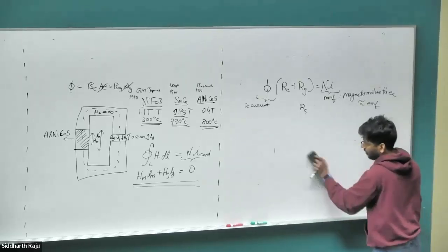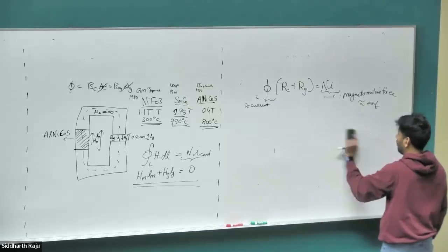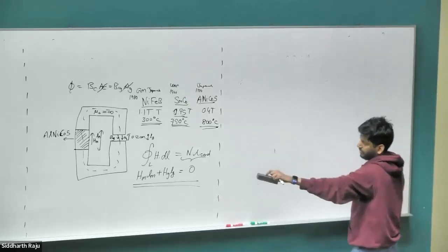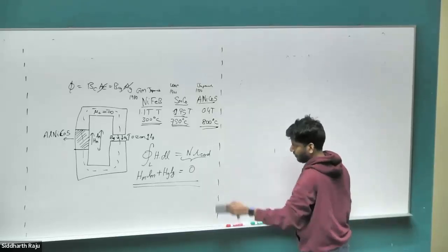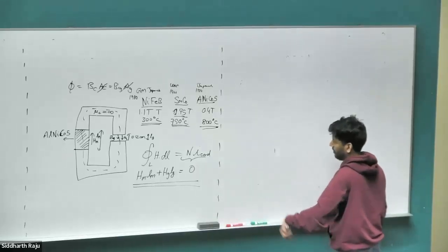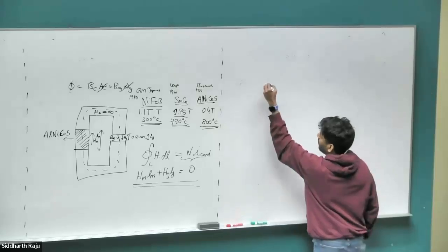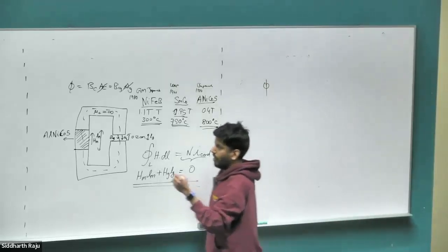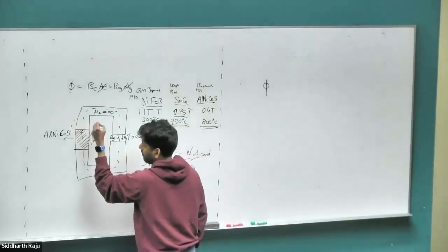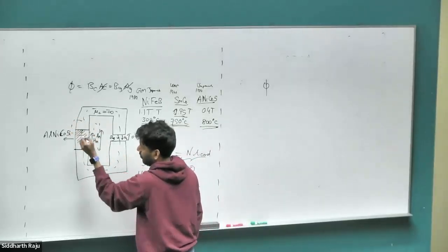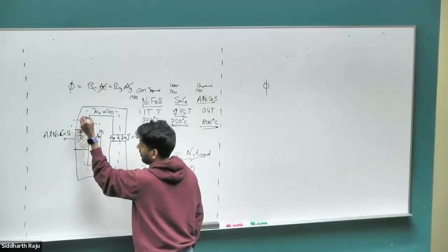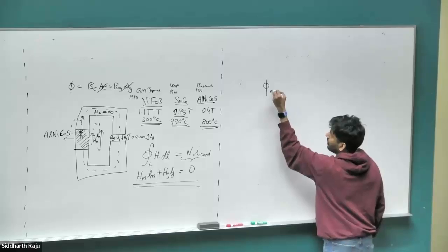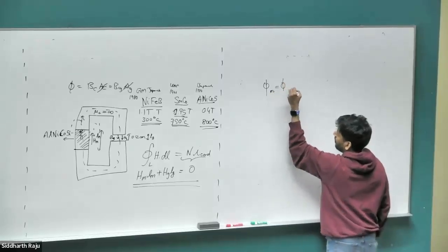Whenever you're given these problems, irrespective of whether it's a motor or any kind of complicated circuit, just figure out what the first equation helps you solve and then figure out what the second equation can help you solve. If you use the second equation, all that it says is if I were to draw any kind of box, whatever flux is entering this box is the same flux leaving the box. That means flux through the magnet must be equal to the flux in the core.